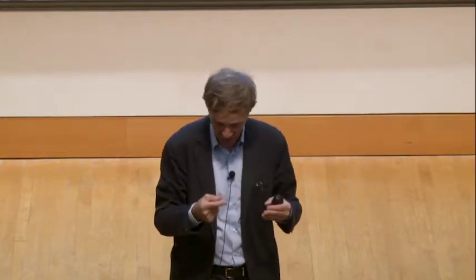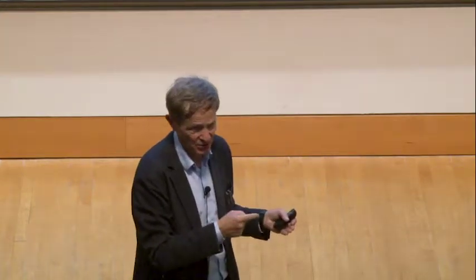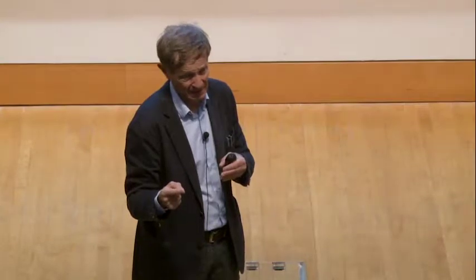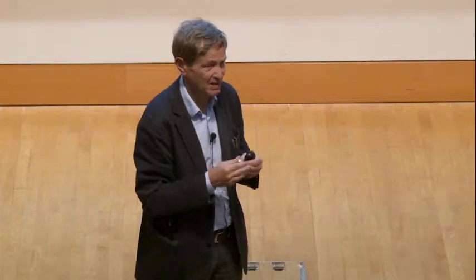And so what we do is we determine the transfer function for velocity fluctuations, the transfer function for equivalence ratio fluctuations. And we characterize the main perturbations, and these are the inputs, and the output is the heat release fluctuation.